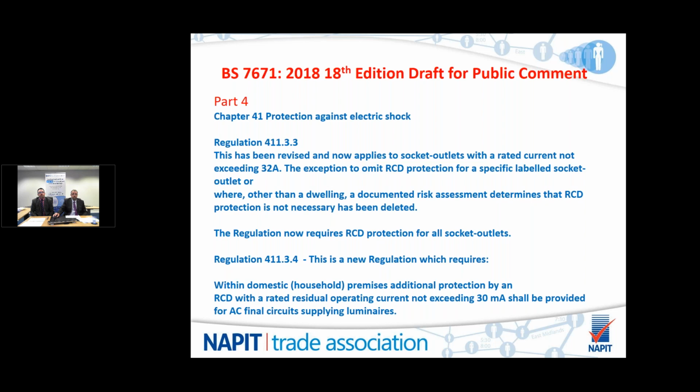Also within this regulation, we previously had two exceptions to omit RCD protection. The first was for specifically labelled socket outlets, which allowed you to put a label on a socket outlet for a particular piece of equipment, and then you could omit RCD protection for that socket outlet. The second exception was, other than a dwelling, you could carry out a documented risk assessment to determine if RCD protection was necessary for those socket outlets. Particularly, this was used in commercial properties.